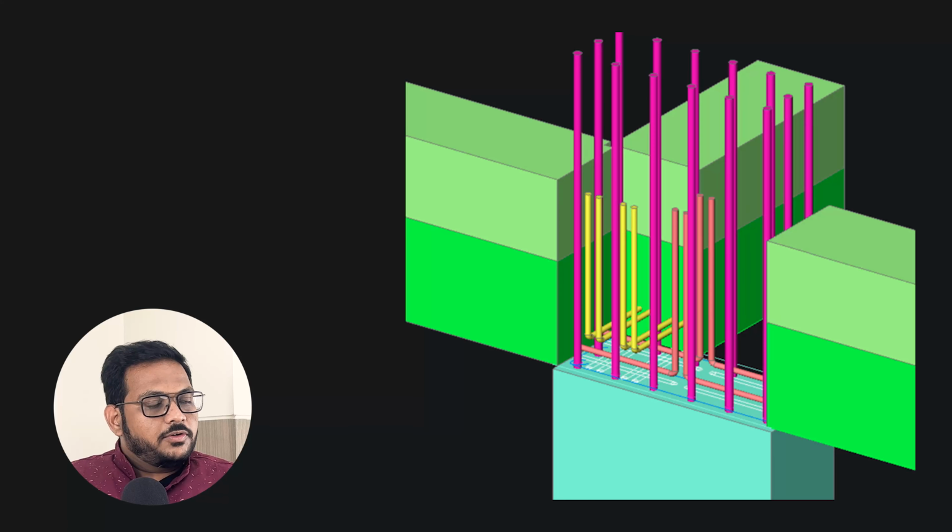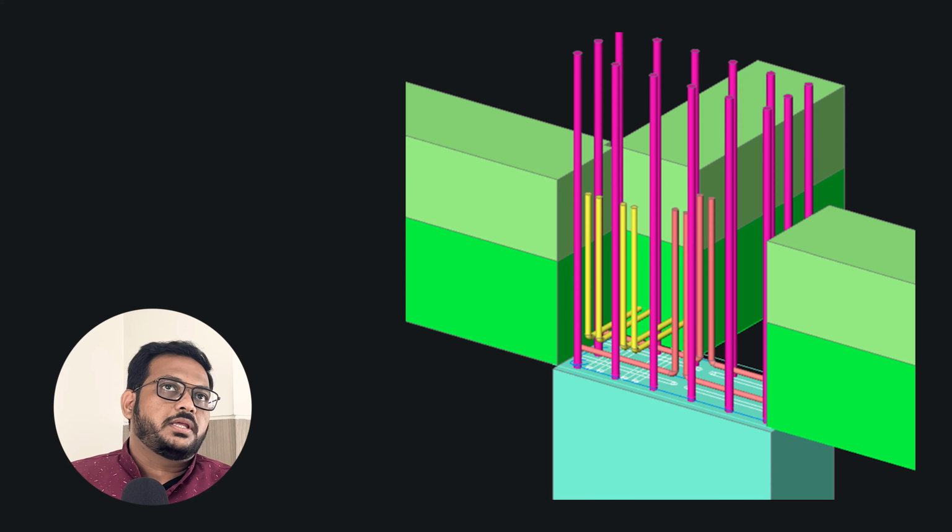And what was the reason that each beam column joint was different? The reinforcement of the column was different at each and every element, every point, and it was heavy. Similarly, the beams were different. Even if the grid size is the same, we had certain differences in the orientation of hollow cores.